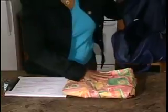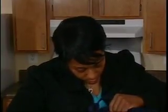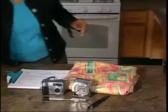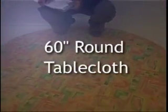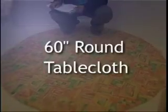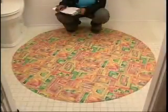And finally, we have a 60-inch round tablecloth. This may seem like an odd item to have in your bag, but the tablecloth will definitely make your job a lot easier when trying to measure a turning radius. The tablecloth is 60 inches round and can be placed in the open areas of the kitchen or bathroom to determine if a wheelchair has enough turning space to make a 180-degree turn.